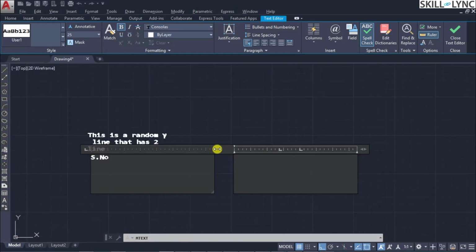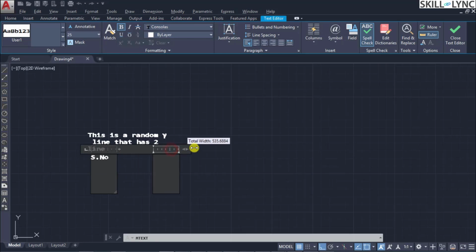See, now the width of the column is mentioned here, so we can dynamically control this width. As seen earlier, we had specified for the dynamic columns the width to be 750 mm, so that is what is mentioned here. Likewise, we can extend it. This is the total width, and now we can expand the width accordingly. But as you could see, the column widths are controlled based on it, so it is uniform in structure.